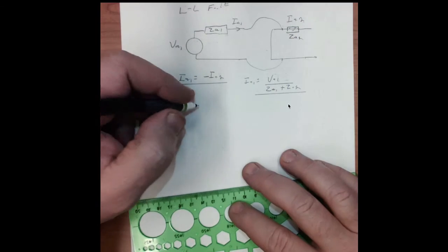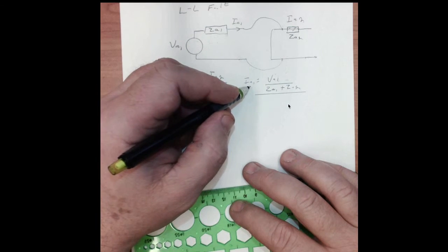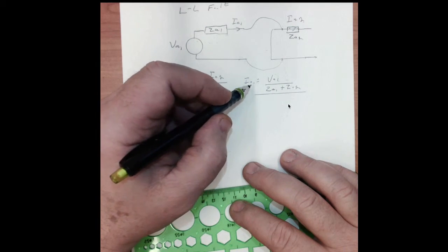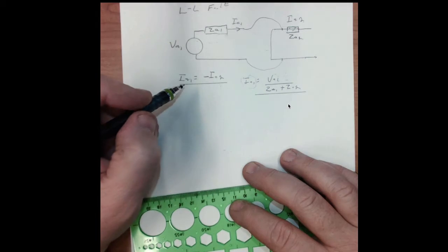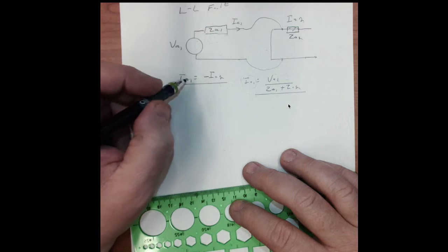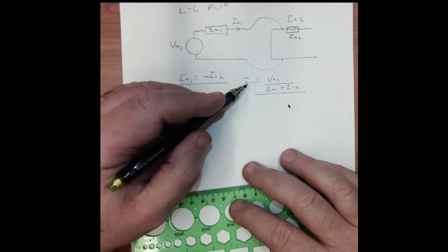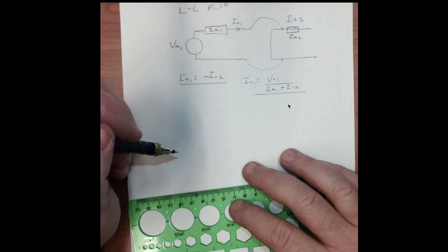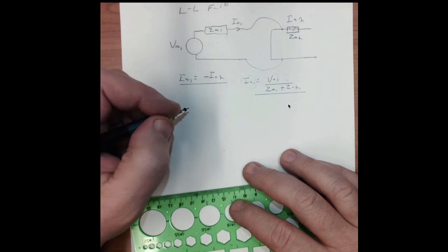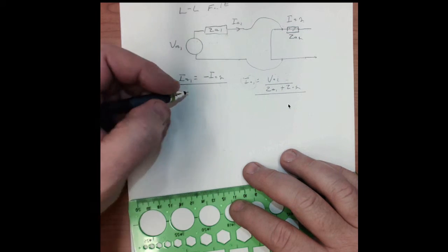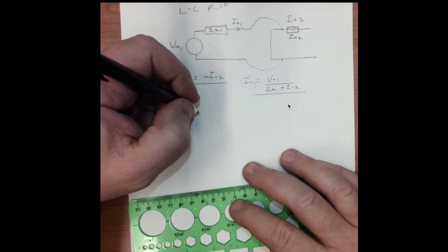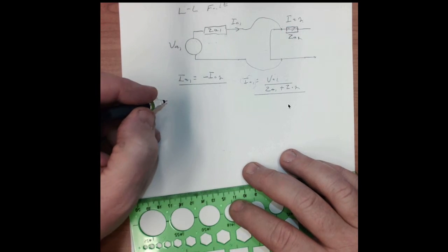At first glance you might say, well, does that mean on a line-to-line fault that our current is half? Well, remember, our sequence current here is going to come out to be a different value, but when we plug these values in, because we now have a non-zero IA1 and non-zero IA2, our actual currents in the lines are going to be significant. So we have to carry through and find our IA, IB, IC.